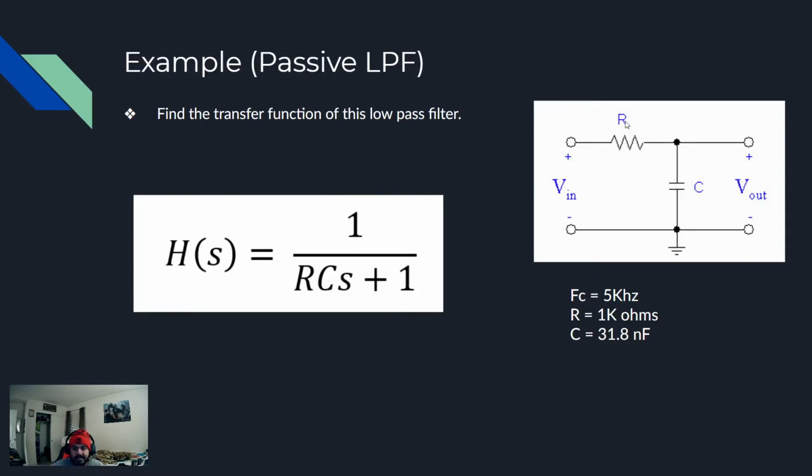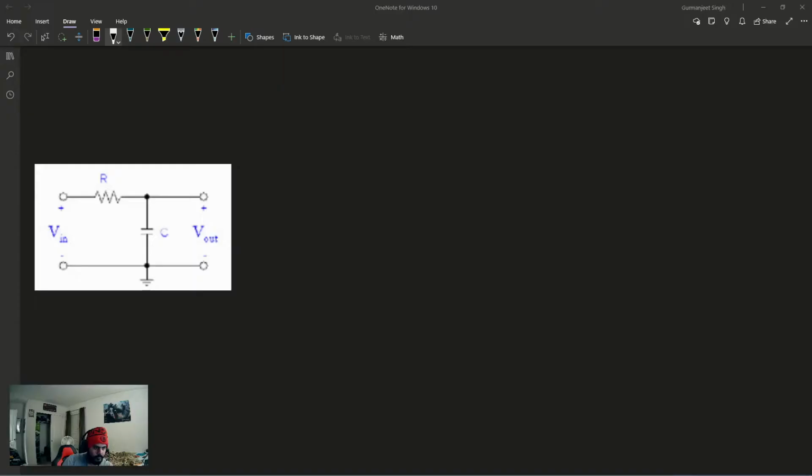So I can set the resistor equal to 1 kilo ohms. Again, completely arbitrary. You can set it equal to whatever you want, but this is when we actually have to use what we have learned within ECE 211, whether it be KVL, etc., to actually find the last component's value. And I'll do that with you guys right here. And by the way, this is the transfer function for this circuit, but I'll be going over this with you guys as well.